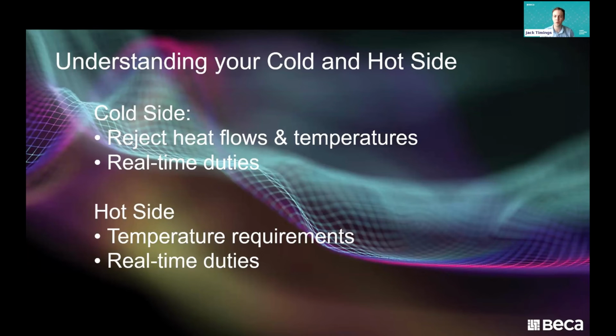So that made it more difficult and was going to be an efficiency barrier to installing a high temperature hot water heat pump. So we spent the time working with the operations plant to run some trials and lock in a control schema that enabled it to work with a more suitable hot water temperature. So those two things actually banked us a lot of savings before the project had even started.